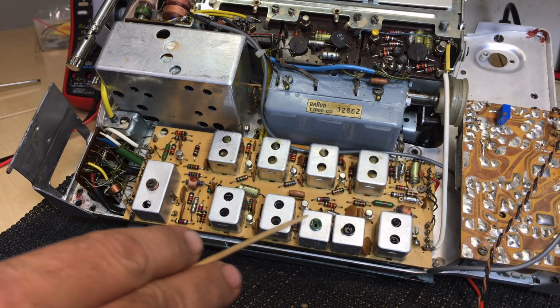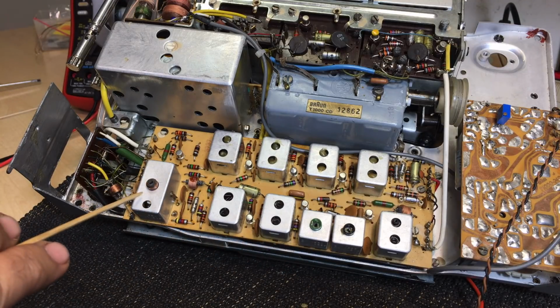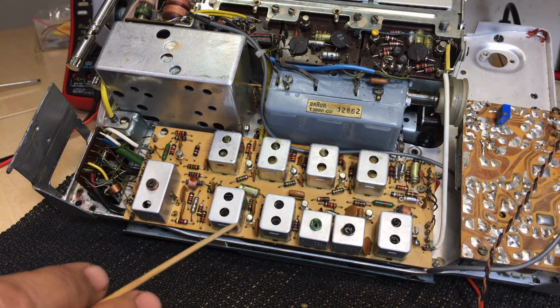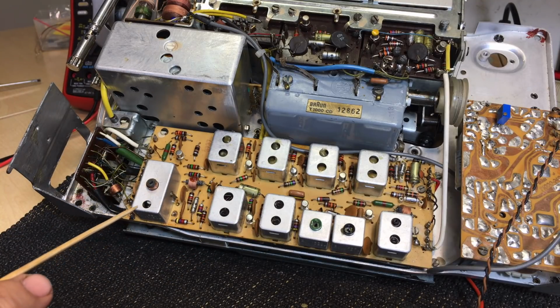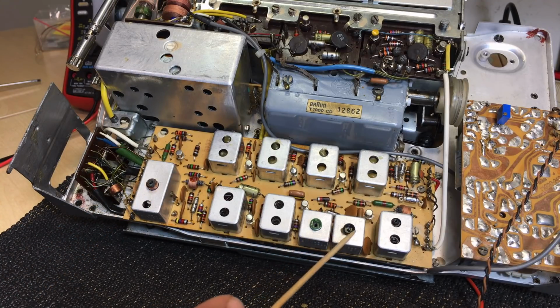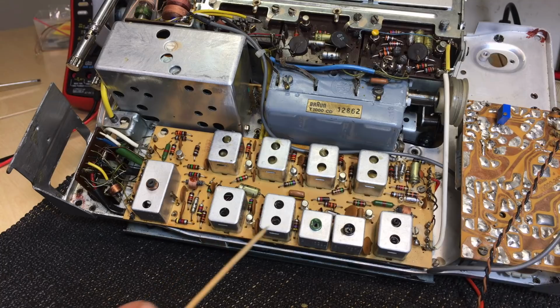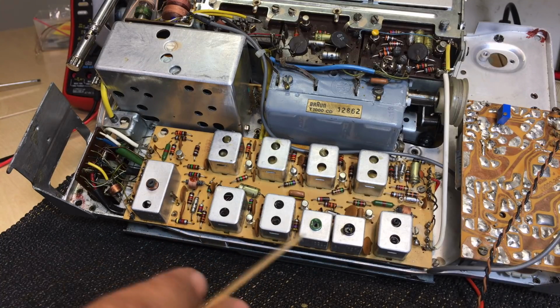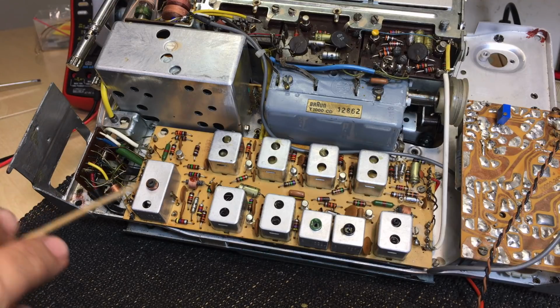It goes through and then it meets this frequency. Now when you sum these two together, you will get two frequencies. One is the frequency sum of the two, and one is the difference of the two. So if this thing is exactly 455 kilohertz, what you get is 910 kilohertz and 0 hertz. Now this is the trick. The 910 doesn't get through because the IF filters stop it. It'll only allow 455 to get through. The 0 hertz is different.